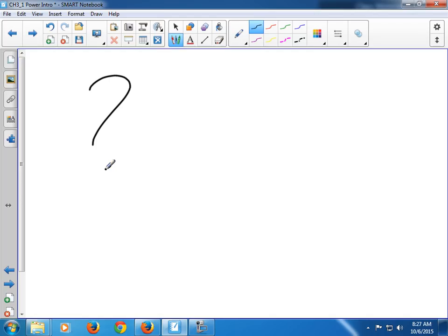Okay, so I plugged this 12-volt one into a CD-ROM. The CD-ROM pulls 2 amps of power. How many watts does the CD-ROM use? Easy math, right? You have to know this is 12. I will not tell you this is 12 on the test. So if you didn't write down, all powers are 12 volts other than the motherboard, which is 3.3, you might want that in your notes.